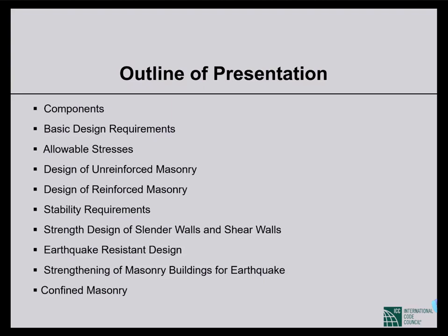That's why even in the case of strengthening or retrofitting, this unreinforced masonry part is quite often dismantled and a new framing system is provided. If we have to have some unreinforced masonry, it can be used as shear walls rather. So that will be my answer to your question.